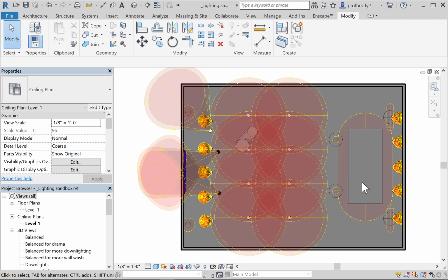So first of all, one of the things I think I've mentioned before is you'll want to see the light sources that are in your light fixtures. One of the most common problems is you'll download something off of sketchy revitcomponents.com and there won't be a light source in the light fixture. Okay, and so this is displaying the light fixtures. Light sources will be the first thing.